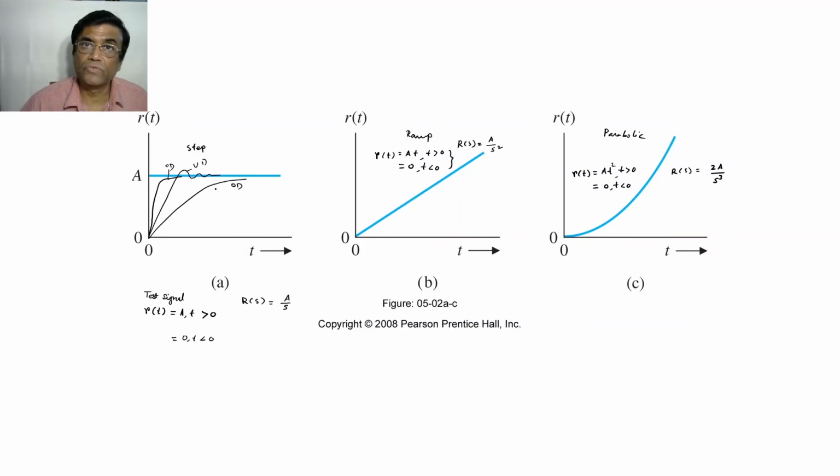Okay, out of these three, which one is preferable? Obviously, critically damped. Why? Because I have asked the controller to move to A immediately at t equal to 0, means as soon as it starts, and this is called settling time, and within very less time it is obeying. So that's why, time and again I told you, the critically damped situation is the preferable criteria based on which the control parameter could be designed.